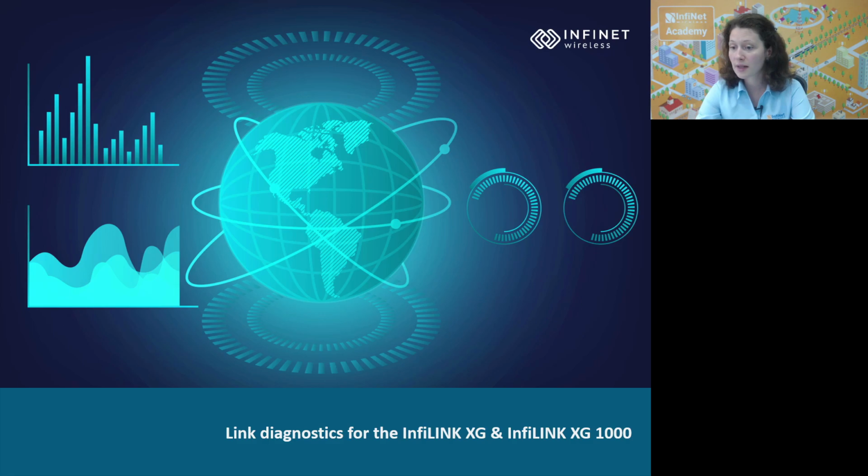If we used an XG or Quanta 5, the RSSI would be constant as the air interface is running at 100% utilization. Yes, once the traffic is stable, you should see a quite constant RSSI level, but an increased level. So if you previously had a noise floor, for example, with no interference, if you activate the interfering link, you should see the RSSI increasing, of course.